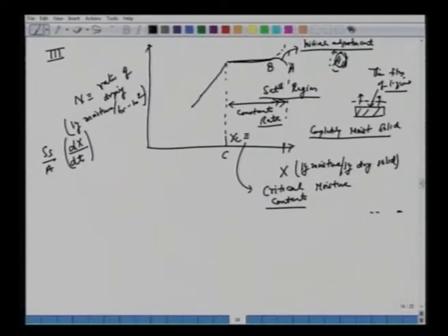This is a typical drying curve, and different solids will exhibit different types of behavior, but this is the most common. The rate is constant, then the rate decreases. So till here we can say that this is a falling rate. We have constant rate and now we have a falling rate, and here we said it's a saturated region.